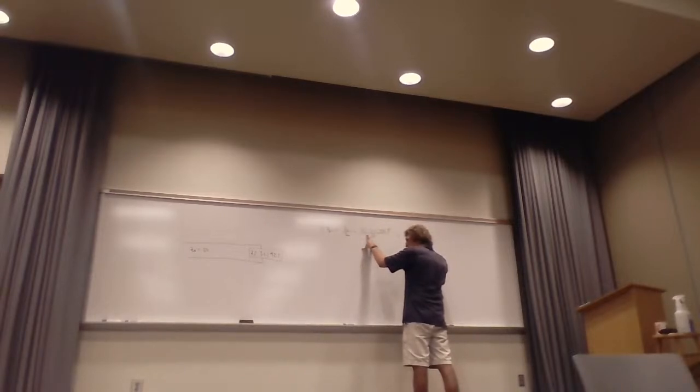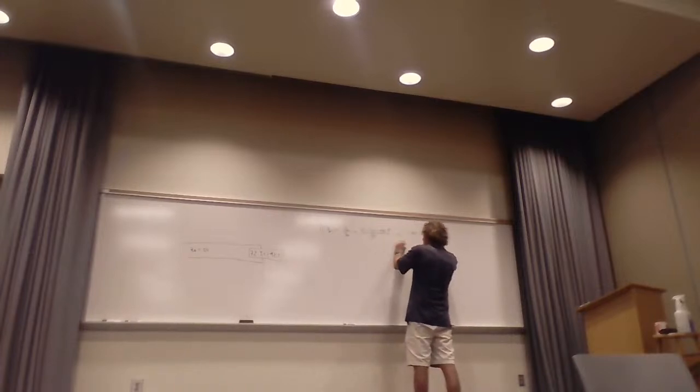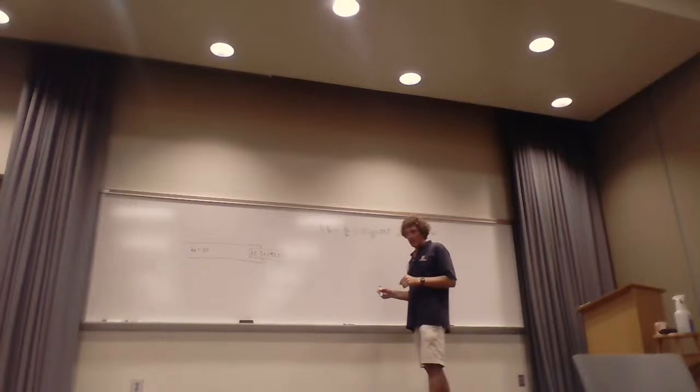It's like 1.48 or something for the real part. 1.45. Okay. Plus J0.85. That's your first point. And this is going to be done in parallel, right? It's a shunt stub. That means we're going to be in the admittance domain. You'll get something like this on a final exam.